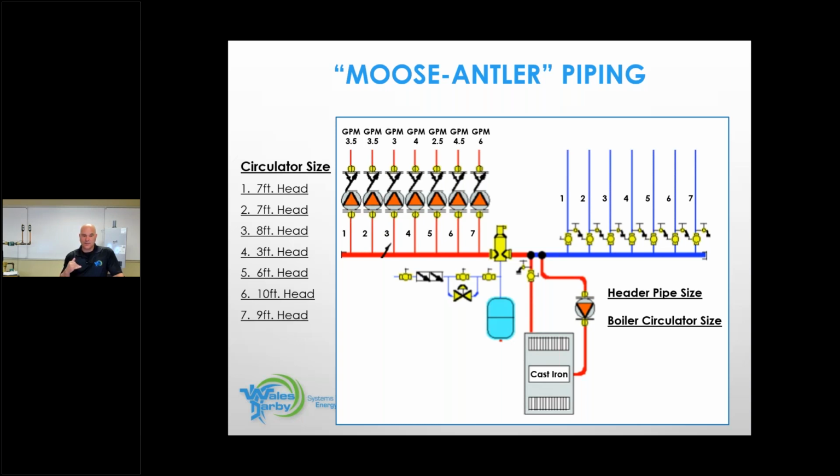Based on your universal hydronic formula, you have a cast iron boiler. I would like to know what the size of that cast iron boiler is. And then if you really want to go crazy, you can do the pipe sizing to go with that boiler size and the circulator size to go with that boiler. So this will take you a little bit of time. Like I said, we did put the majority of it out there for you. It's really just going to be looking at circulator curves and picking circulators. So start that exercise and go from there.